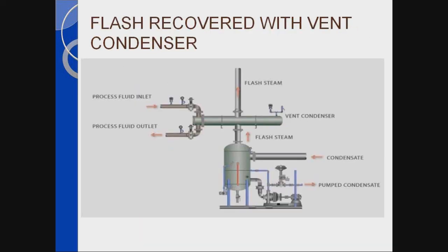To recover this becomes a little more difficult, because this tank pressure, as we're showing in this diagram here, has to be 0 psi. If it's 0 psi, I cannot cascade it, and it's very difficult to thermocompress it. Therefore, to deal with it, I go into a condenser.